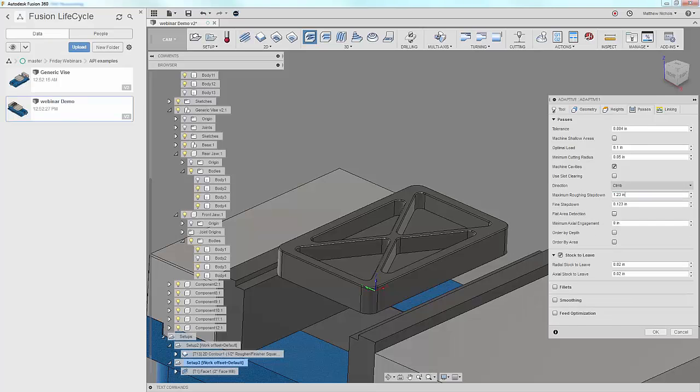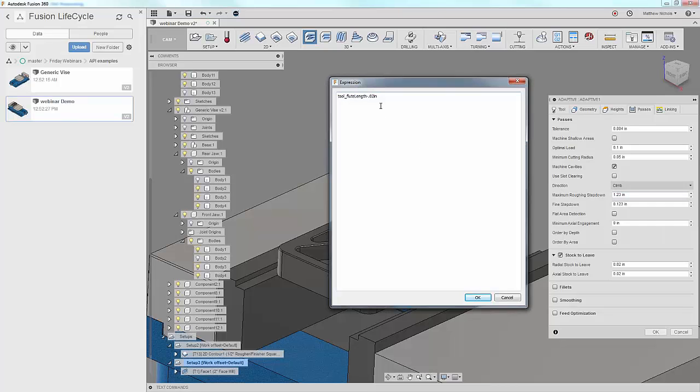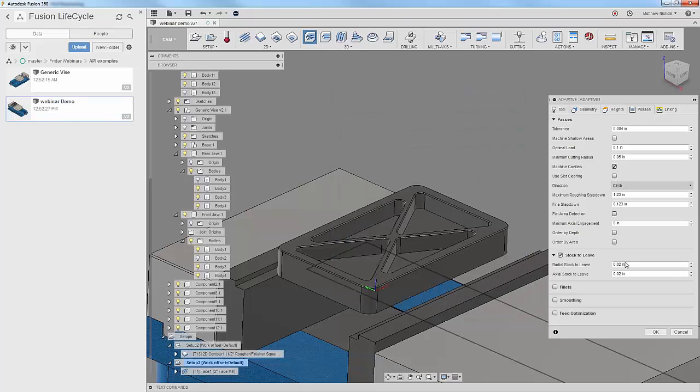And then one thing you always got to remember, if you actually do want to put an inch value in here, you have to make sure to put the IN marker for inch. If you don't, it'll revert back to metric. So a little quick tip on that one.